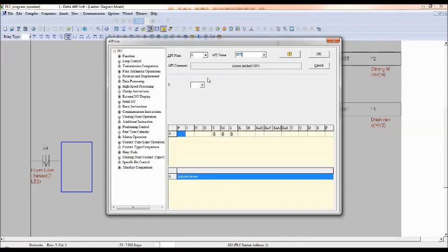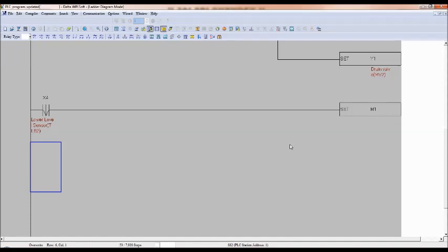M1 is a marker or memory bit. Initially, at the time of filling, the low level sensor will be on. Again, when the tank is really empty, the low level sensor will be off. So at that time I am using one memory bit.